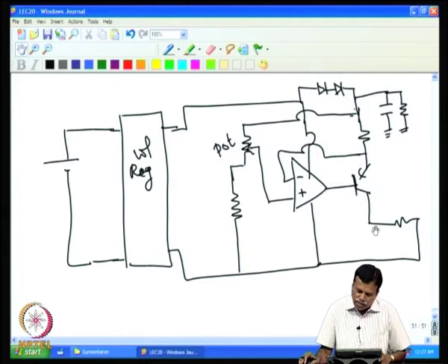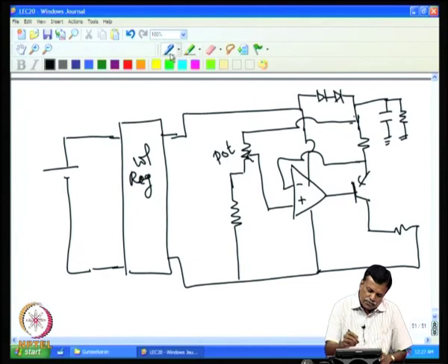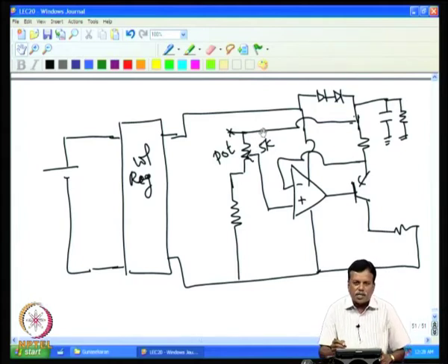Similarly, when the other end is there, the voltage may not have reached its full value, the potentiometer may stop a little away from the end. For example, if this is a 5K pot, and I take this as one end of the point, then when the potentiometer is moved to this extreme, I should get 0 volt across this, but that may not be exactly 0.